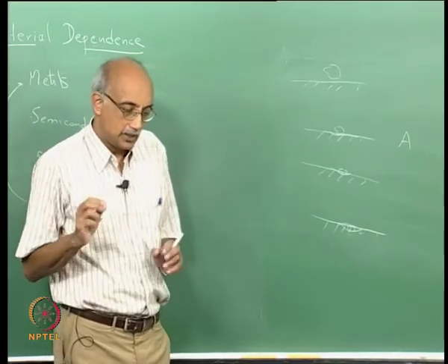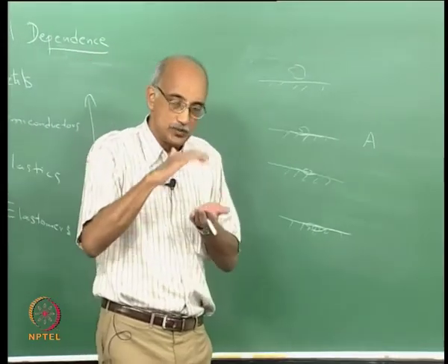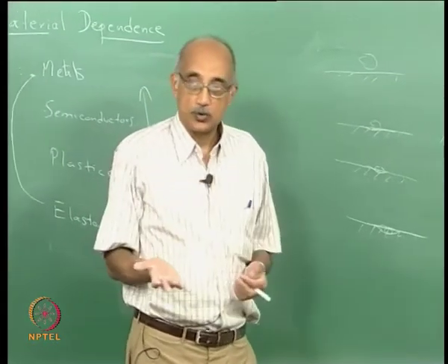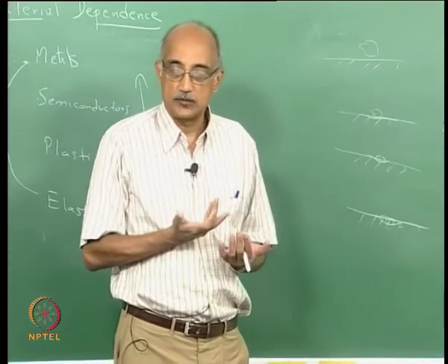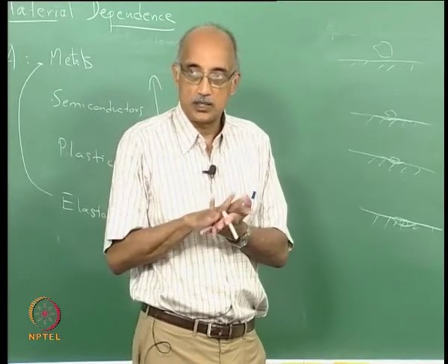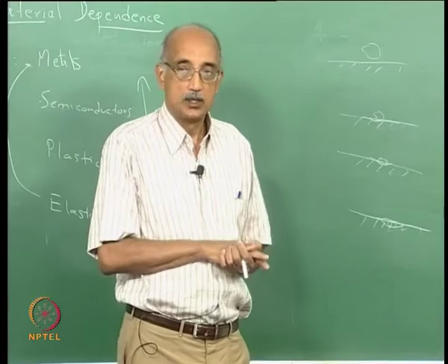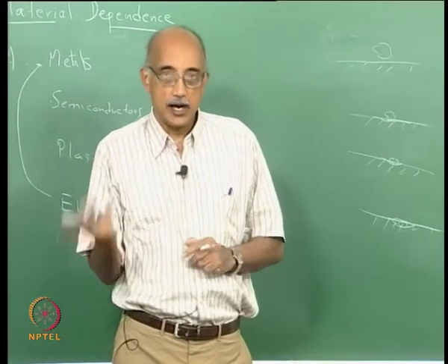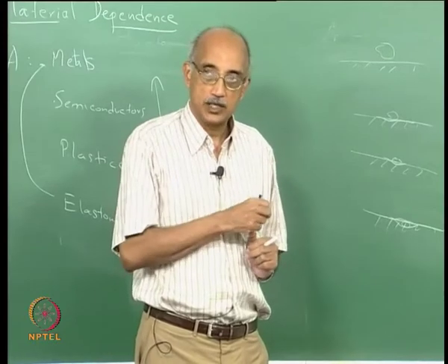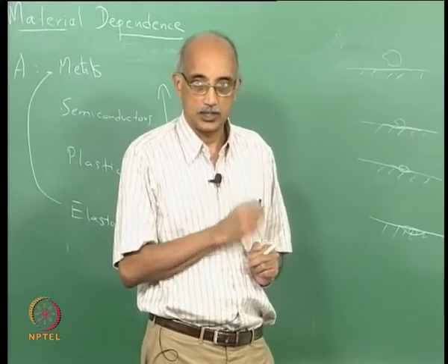So basically when you have two rigid particles in contact with each other and you estimate the adhesion force associated with that and compare it to a case where the two bodies are now considered to be deformable, the adhesion forces that develop in the latter case can be orders of magnitude higher compared to the adhesion forces that develop in the first case.